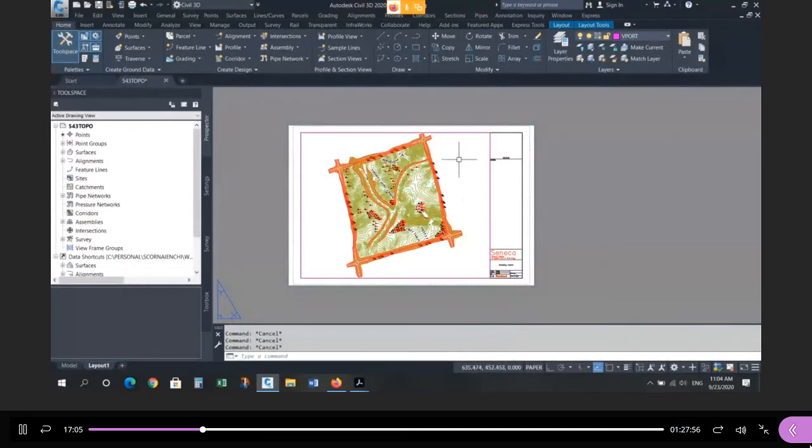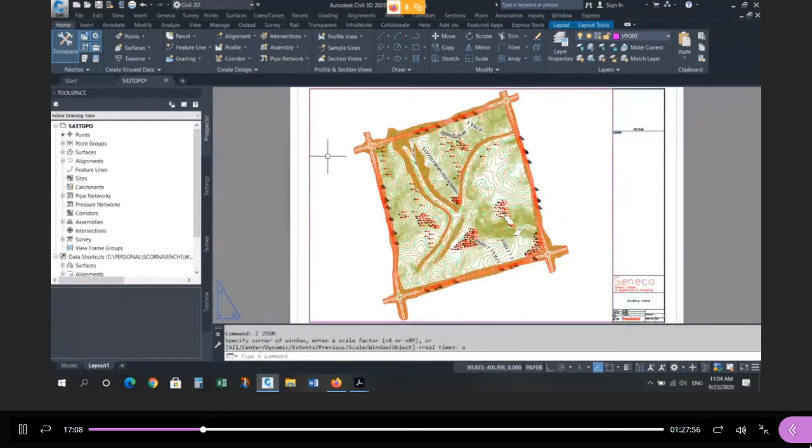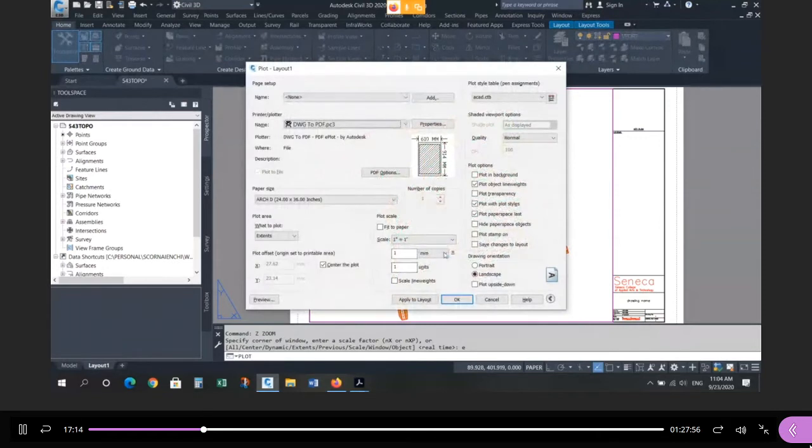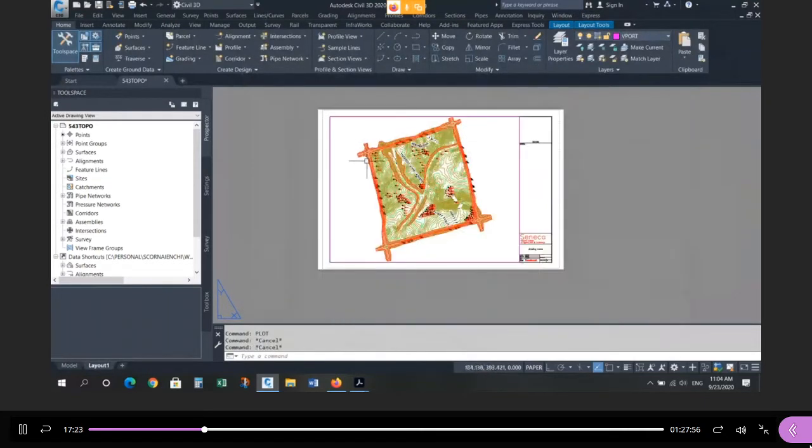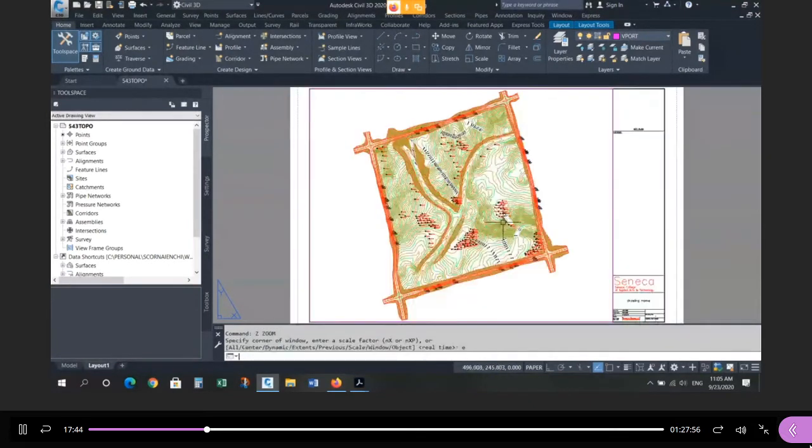And now the scale. A couple of ways of establishing scale. Okay, the first thing you want to do is ask what's an appropriate scale for this size object? Okay, well, the paper scale is always going to be 1:1. We're always going to plot at 1 millimeter equals 1 unit, which on paper is 1 to 1,000. Okay. However, we can manage the size of the object. We can change the zoom factor, change the scale of the drawing without having to change the plotting scale. Okay. So what happens is if anybody opens this drawing, they just plot it. It's always 1:1. But whoever set up the drawing, they can change the zoom factor and have different scales on the drawing. Okay. In this case here, we will use a 1 to 1,000 scale.